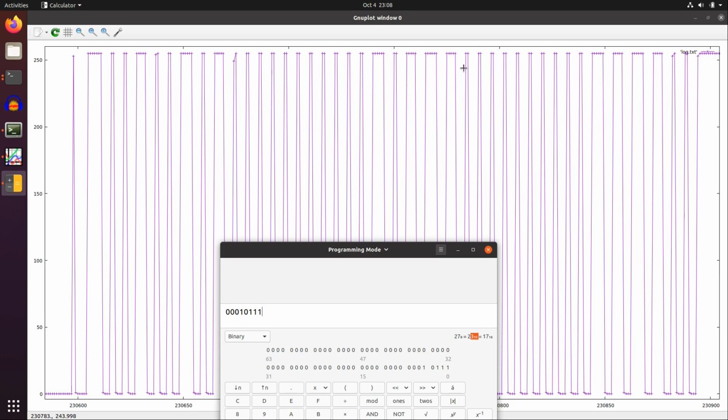Same here, the next 8 zeros are for the decimal part. But the DHT11 does not have any decimal part. The resolution is plus minus 1 degree. That's why the next 8 bits are always 0. 1, 2, 3, 4, 5, 6, 7, 8. This is followed by a checksum.